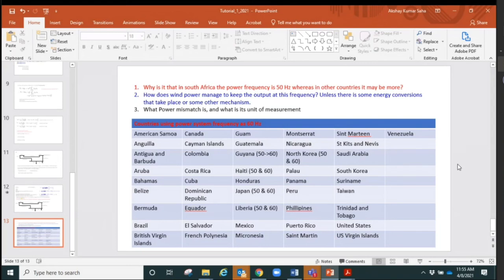So they control the generator to the values we calculated, like they try and match those two. Yes. But again, this difference will be reflected in terms of the frequency, in terms of the voltages. That's why we look at the voltage. The reactive power will be reflected on the voltage, active power will be reflected on the frequency.